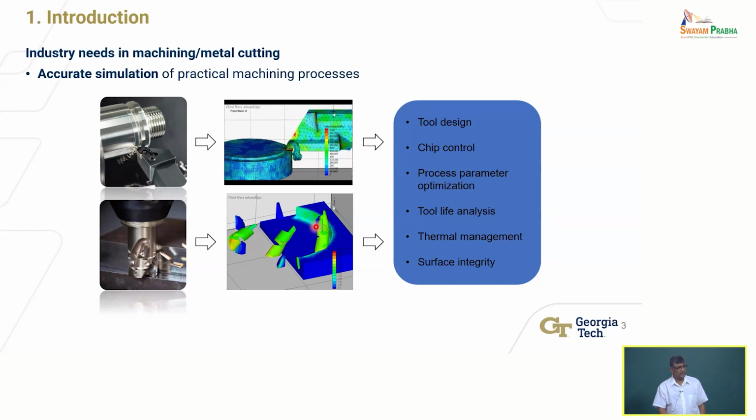But there are many applications. These tools are being used today in industry. They're being used for tool design. As most of you who have had any exposure to metal cutting, whether turning, milling, or drilling, have seen, cutting tools have complex geometries, even lathe tools. The disposable inserts have all kinds of geometries, and you wonder how they came up with those geometries. They have all kinds of chip breaker control geometries designed in them.